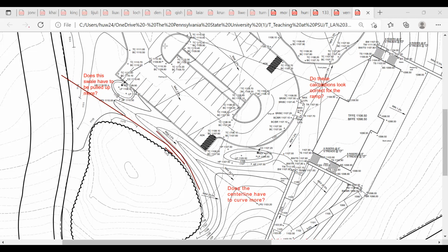Yeah, I'm trying to be as tight as I can. Can I not have them go into the parking lot like that on the top? Like I have them coming out on the side and then going into the parking lot and then connecting around the other side? Do I still need to connect them at the bottom? Right. But you can't have 13 and 12 next to your 9 contour. You have 13, next contour is 9, right? Right. Yeah, so we're missing a couple of contours there.